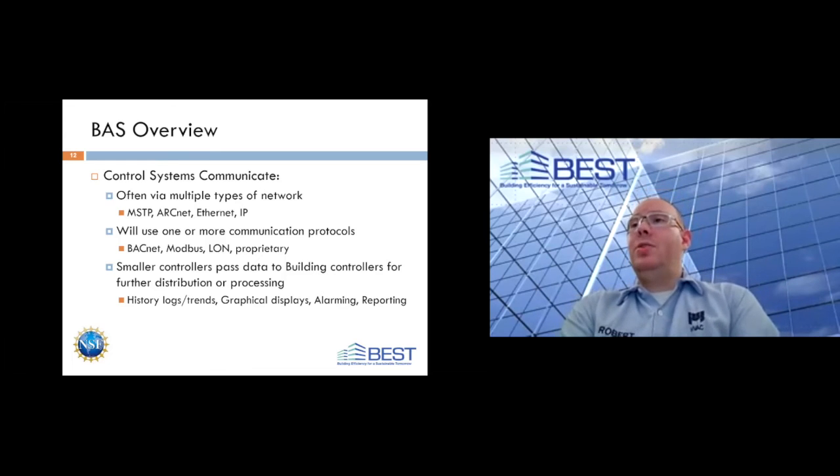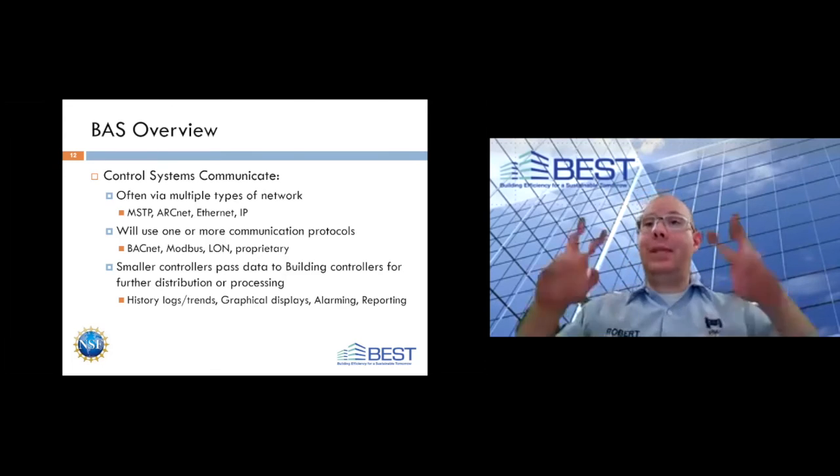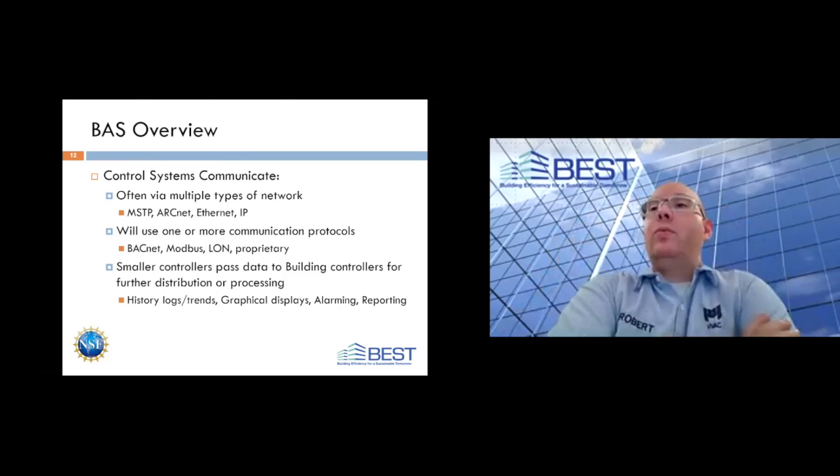BACnet is a fantastic protocol. It's a common language, so even manufacturers that make factory controls for their air handlers or chillers, like Trane or Daikin, their systems may talk BACnet. So it's an easy integration with your system.